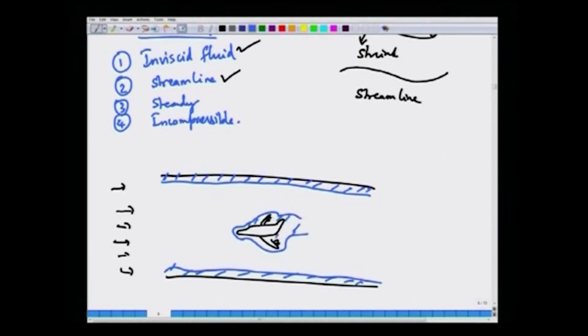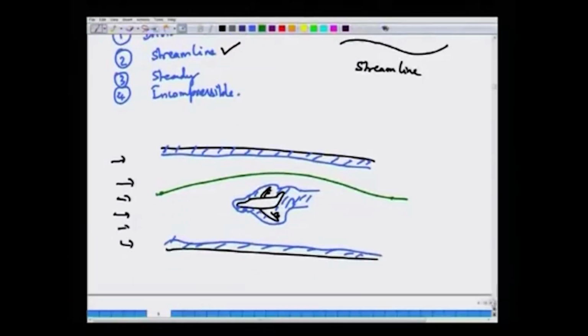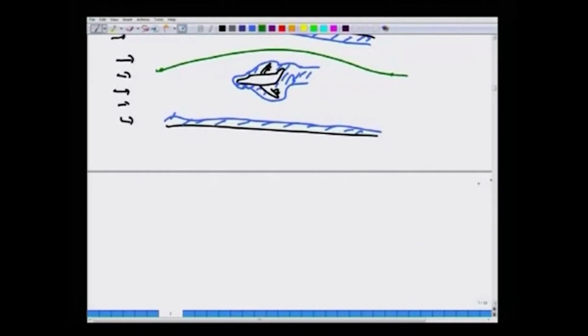There will be viscous effects that are very important. So, the Bernoulli equation will be invalid in the blue patches, but if you take a streamline where there is no blue patch, then you can certainly apply the Bernoulli equation between these 2 points, because you can assume, to a good approximation, that viscous losses are negligible. They are never 0, but they are not that important, okay.